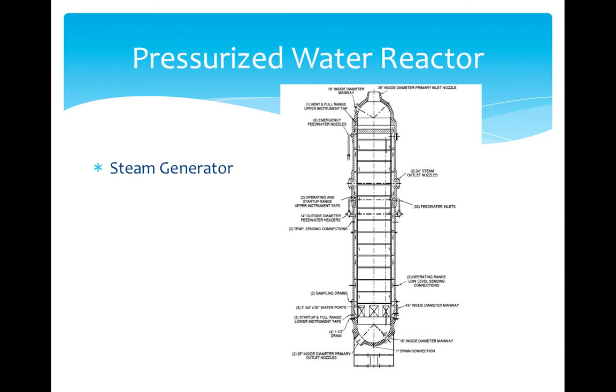Inside the steam generator, hot reactor coolant flows inside many U-tubes. The secondary coolant flows around the outside of the tubes where it picks up heat from the primary coolant. When the feed water absorbs sufficient heat, it starts to boil and form steam. There are many different variations of a steam generator depending on the design that's being used. However, all of them pipe the steam to the main turbine. Shown at the right is a Babcock and Wilcox once-through steam generator. This design was used in the Three Mile Island plant.